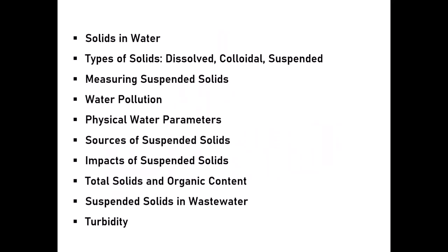Dissolved solids are tiny molecules or ions less than 10 to the power of minus 6 millimeter, invisible and not removed by filtration. Colloidal solids are small, behave like dissolved substances, with size from 10 to the power of minus 6 to 10 to the power of minus 3 millimeter. Suspended solids are larger than 10 to the power of minus 3 millimeter and can usually be filtered out. Knowing the size of solids helps choose the right treatment process.